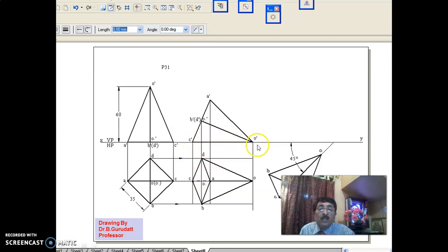That is why when a slant edge which is on HP is inclined at 45 degrees, since it is true length only, we don't have to undergo beta construction. Directly tilt it, that is move, copy and rotate such that OC, not top view of the axis, it is OC slant edge which is inclined at 45 degrees to VP.